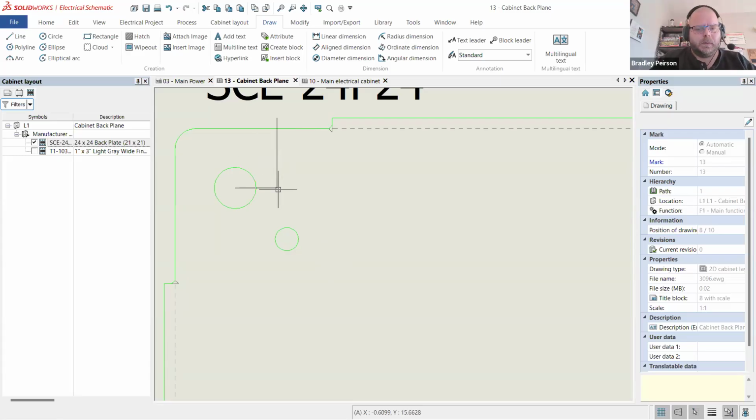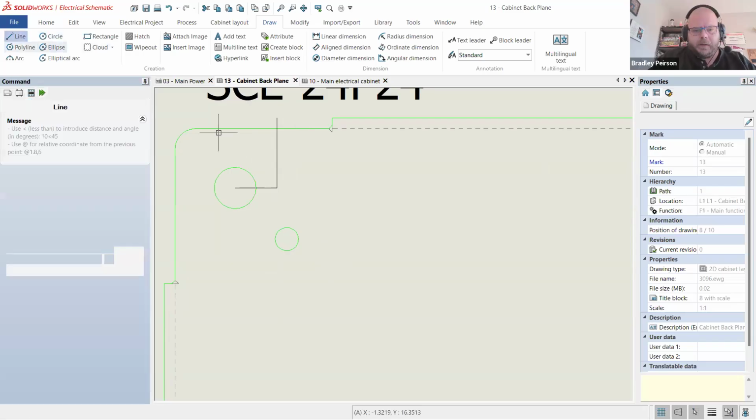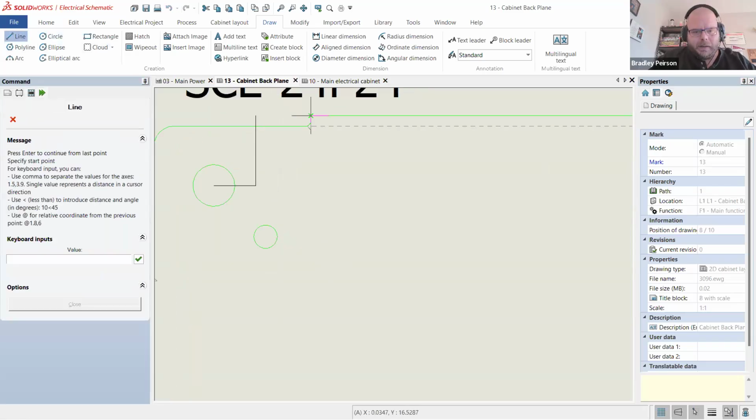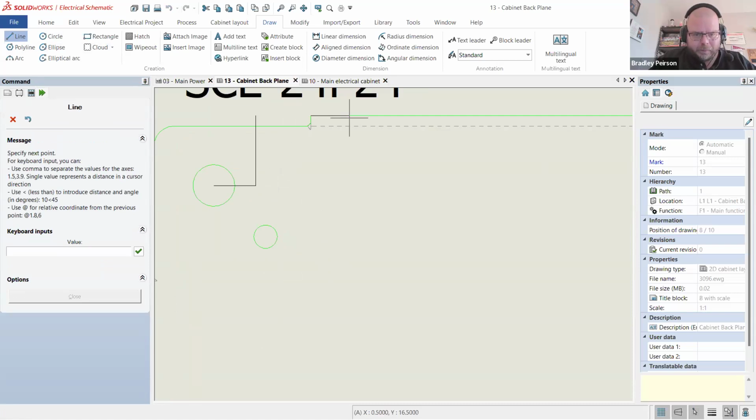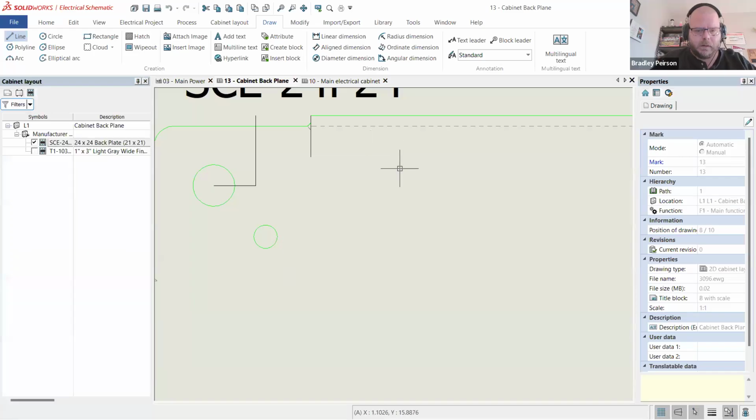So I can basically start there, go this way, and then come down with the vertical and be absolutely fine. But our duct is an inch wide, so I need to come down from the top here because this is where somebody's going to put their ruler, this far edge. Come down from the top at 0, comma, minus 0.5, right?